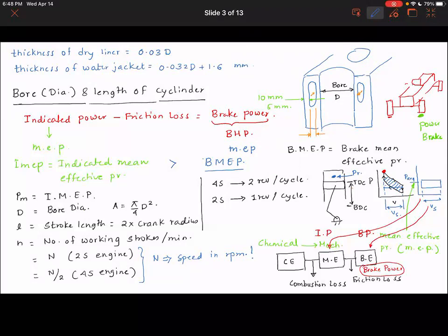So if for some reason there is variation in the fuel quality, or the temperature of the cylinder goes higher, say it has insufficient coolant, then you have something called the exhaust gas recirculation EGR valve. That EGR valve would open, and it will mix the burnt spent gases with the incoming charge to reduce the quality of the incoming charge.